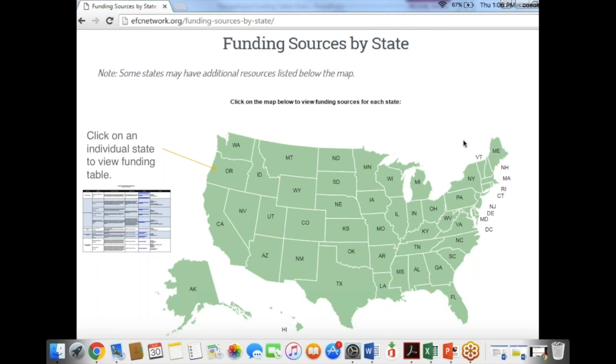One utility had a bunch of valves, and it turns out some of their valves turned to the right and some of their valves turned to the left. And you can imagine the problems that might occur if you go out to operate a valve and you're not sure whether it's a right valve or a left valve, and you don't know which way to turn it. So you're going to break a lot of valves that way and cause yourself a lot of trouble. So think of the extra work you create by either breaking a valve or trying to spend a lot of time figuring out which way they turn.